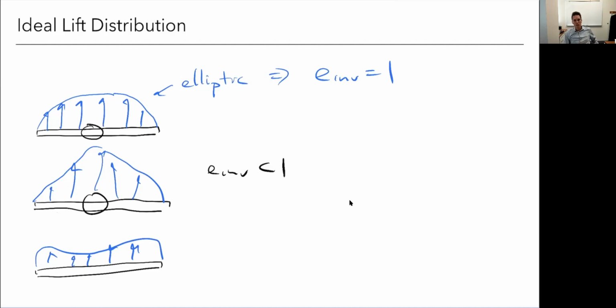So we can actually even do better than E inviscid of 1, but that means we need to be non-planar. Like if we had winglets, you can get a little bit higher. We're of course also adding parasitic drag though, because now there's more wetted area, so it's not necessarily an obvious win. We've also added maybe more weight because now we've got bigger bending moments. So again, a trade-off there, but in general, many airplanes, not all, but many airplanes will have close to an elliptic lift distribution because of this property. All right.